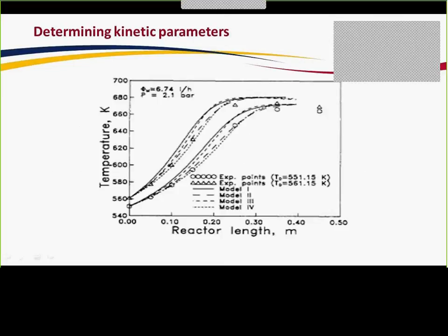So we began our derivation by examining a temperature versus reactor length plot for the high temperature catalyst. We made the assumption that at the very start of the reaction, the methanol mole concentration would be approximately equal to 1, which reduced our final rate expression. From there, we recreated the packed bed reactor in Aspen HYSYS and constructed an Arrhenius plot by taking two data points as seen at the very start of the reaction.